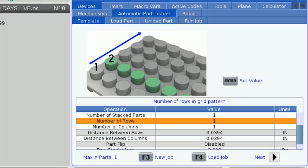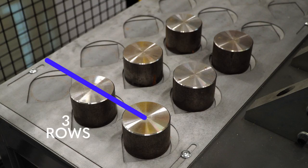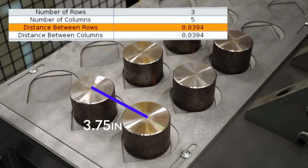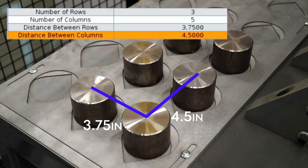I am going to be using the default template that comes with Haas Robot Package 1, so I'll use the dimensions listed on the machine layout drawing for these rows. The drawing tells me that I have 3 rows and 5 columns. The distance between the rows is 3.75 inches, and the distance between the columns is 4.5 inches.